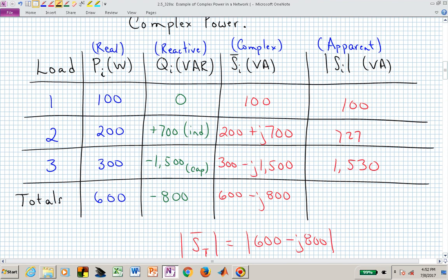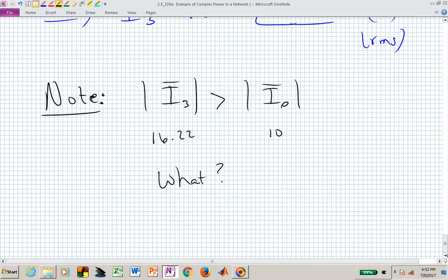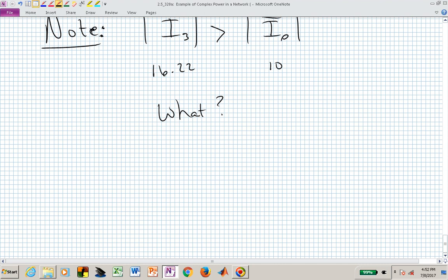And in fact, the current at loads 2 and 3 is really sort of being passed back and forth at the load end, and so the source doesn't need to be delivering quite the amplitude of current that's actually required at the load side, or the load side being loads 2 and 3, than what's required overall.